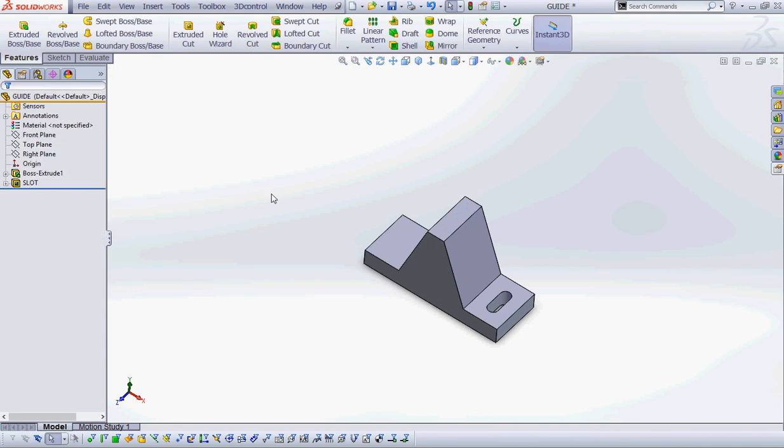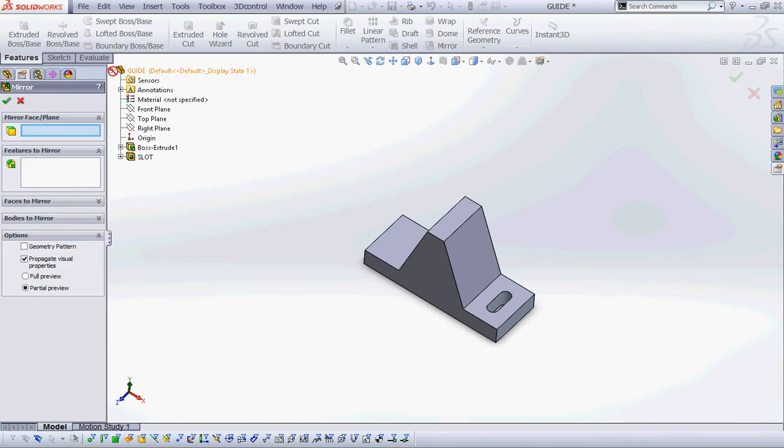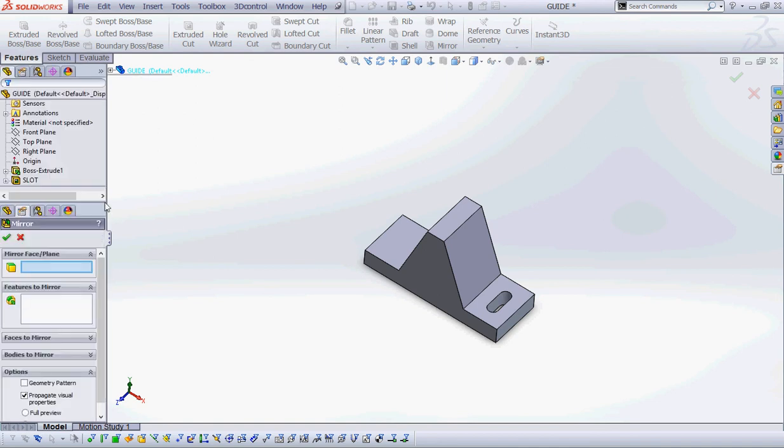Whereas if we did it in a sketch, even if we did equal on the dimensioning and equal on the length and link the dimensioning and all that, it could create issues in terms of maintaining it, right? Extra work. Reason number 2 is that if you mirror it as a feature, your file size isn't as big.